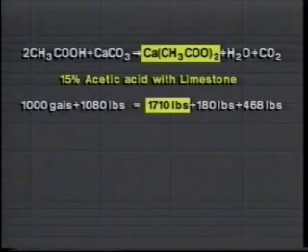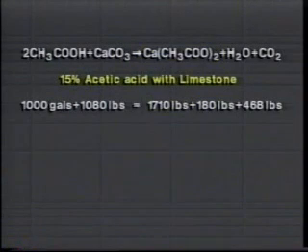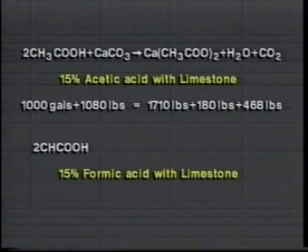The resultant calcium acetate is a calcium salt and is of little concern since it is generally soluble in the spent acid. Because of its low corrosivity, acetic acid is also well suited to situations where aluminum or chrome-plated parts will contact the acid. Formic acid is stronger than acetic acid, but weaker than HCl.